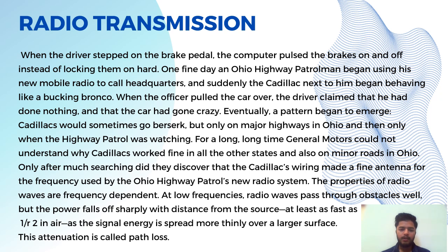The properties of radio waves are frequency dependent. At low frequency, radio waves pass through obstacles well, but the power falls off sharply with the distance from the source, at least as fast as 1/r² in air, as the signal energy spreads more thinly over a large surface. This attenuation is called path loss.